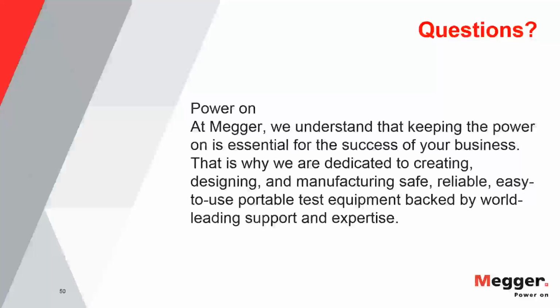So you can do PD analysis and, to a certain extent, PD localization, for instance, on switchgear, or high voltage or medium voltage end terminations when it's coming into the substation. Transformers, like your high value assets, are typically targeted with online and in-substation handheld applications. But again, the apparatus is different, the principles are different, and for the cable testing specifically, for the cable assets, you want to do offline testing because that's the only really suitable way of doing that.